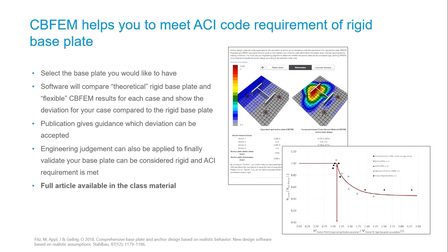How do we do it? We have done a lot of research and a lot of tests, and finally we came up with what I think is a simple solution. We compare the anchor forces. Let's just assume a bending, rigid base plate with reinforced concrete theory and whatever. You can basically say, okay, here is my compression, here's my tension. This is then the tension calculated. Easy.